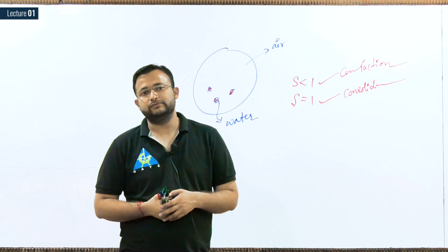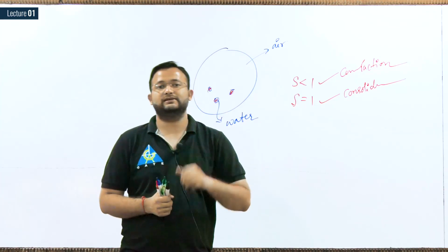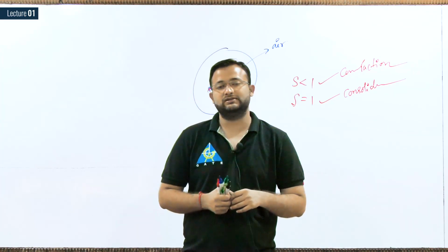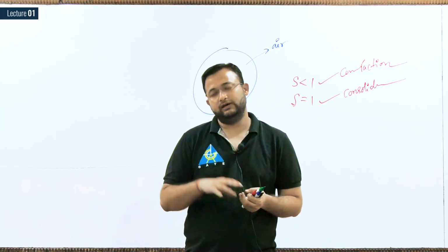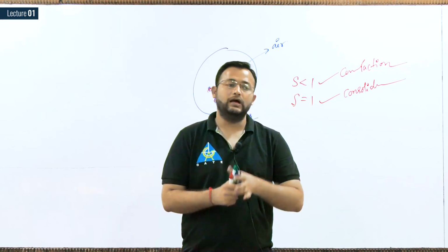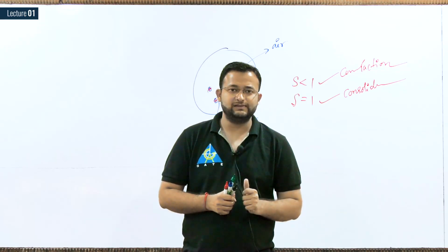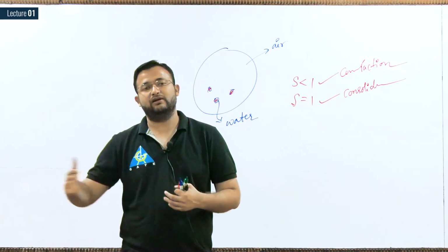Now the question comes, sir, we understand compaction can be performed before the construction of a building, consolidation can be performed after the construction of a building, because compaction is an instantaneous process, immediately we get the results, but consolidation is a time dependent process, it takes a lot of time.